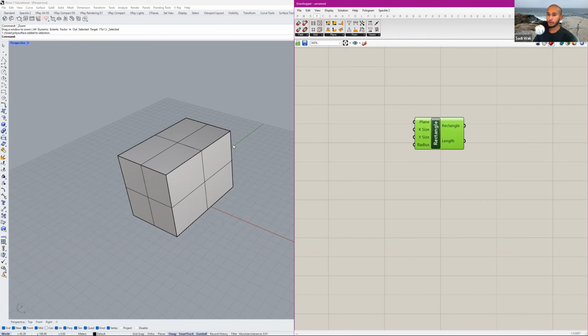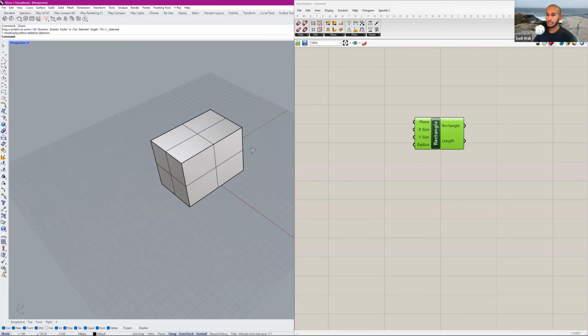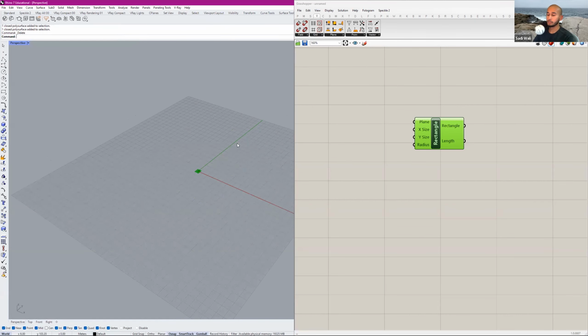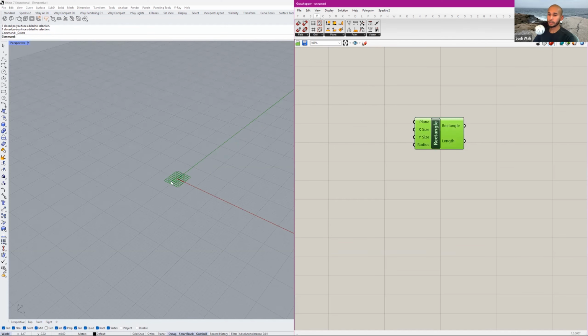When you brought this component in, you might not see anything because this block here is actually hiding it. So we'll just get rid of this block. We don't need it anymore. Right away, you'll see this red thing appear, and if you click on it, it highlights in green. That's already creating a rectangle here. It's hard to see, but there's a rectangle that's 2 meters by 1 meter. The Grasshopper units are the same as your Rhino units, and in this case, it's in meters for us.